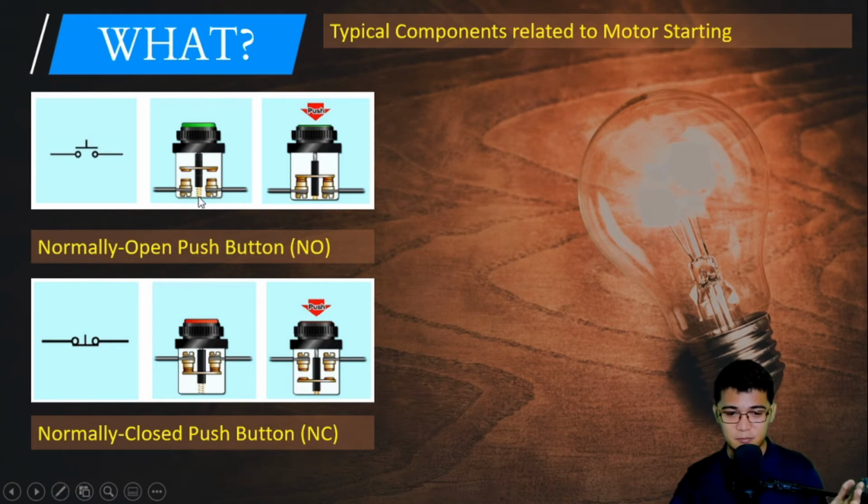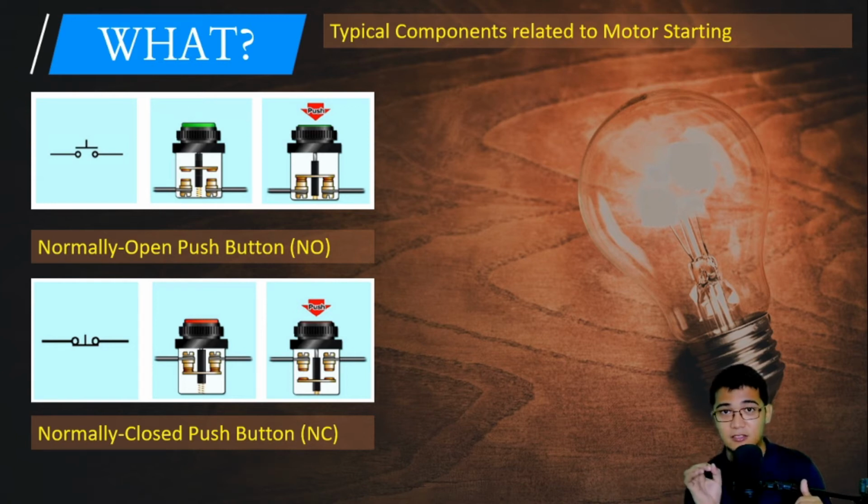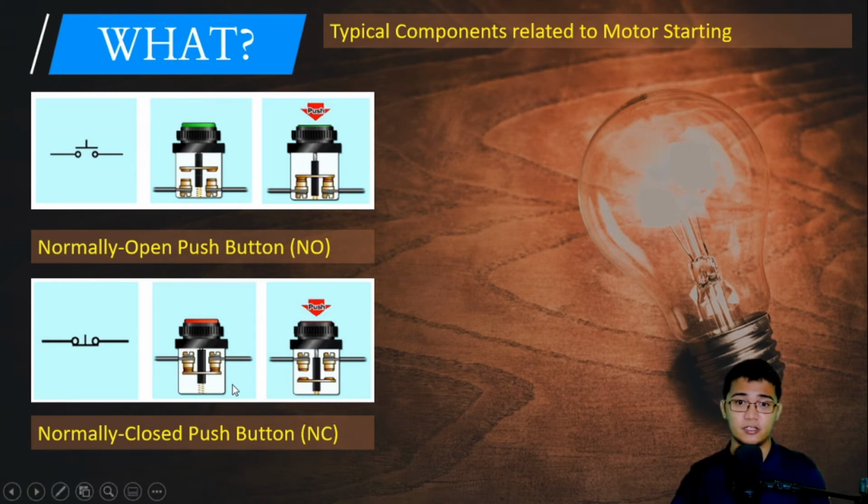So this spring, whenever we push this button, yung spring is magre-retract. But when we remove our finger on the push button, the spring will actually go back to its original position. Same with the normally closed na push button. So those are the different kinds of switches that we will be encountering in motor starters.